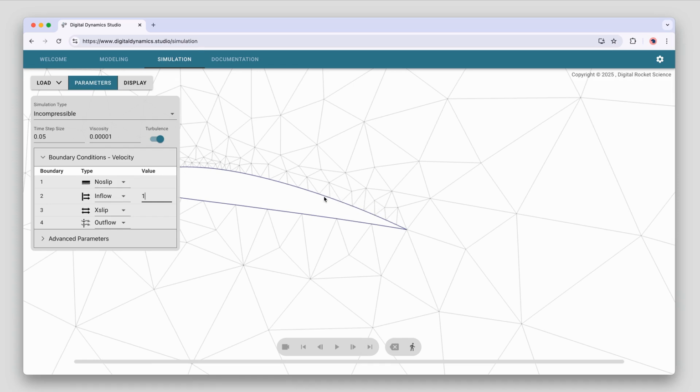But that's a detail of the boundary layer. Yes, it's super important, you want to know what's happening with the boundary layer, but if you're just looking for what the flow looks like, what is the lift value, what is the drag value for the airfoil at different angles of attack and different shapes, one thing you can do is just ignore the boundary layer. We can do that by applying a slip condition instead of the no-slip condition.